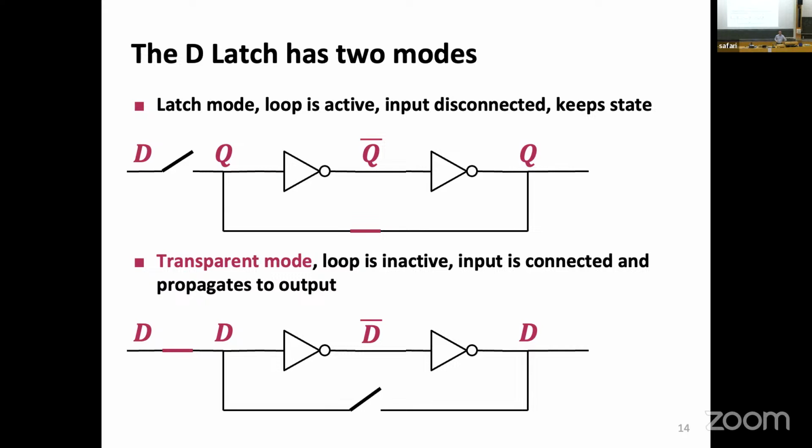We will first see processors, and then we will go into memory systems, and then we will talk about the different types of memories we have. We will move from what we call CMOS logic, registers, SRAMs, DRAMs, and then we will come to hard disks and non-volatile memories, and how they store. The principle is the same. Somehow you have to keep a 1 or a 0.